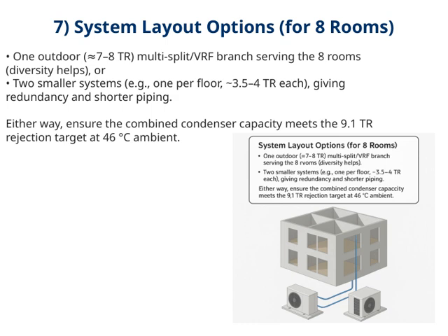Connecting these points, the main takeaway is that both options have their merits, but the key is to match the condenser capacity to the cooling load, especially considering the climate conditions. This helps us design a system that's both effective and resilient in serving all 8 rooms.